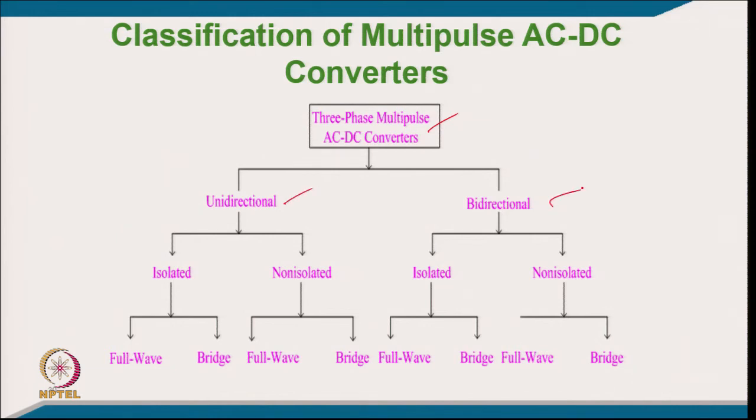Unidirectional use the diodes and bidirectional use the thyristor. Earlier in some applications we were using a thyristor, because we require output voltage control, but it certainly requires reactive power burden. Harmonics go on reducing with a high number of pulses, but the reactive power burden is there.